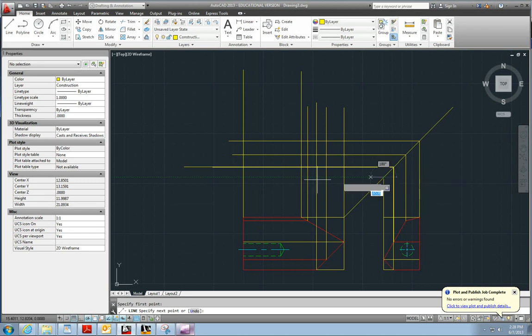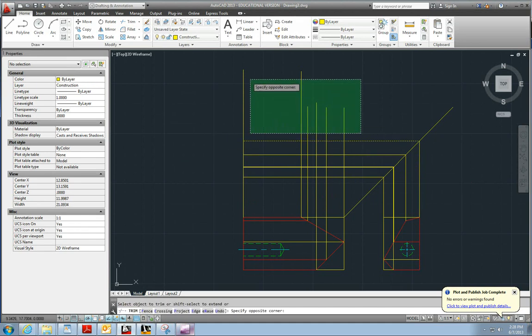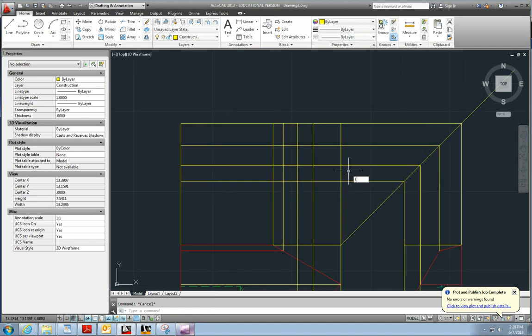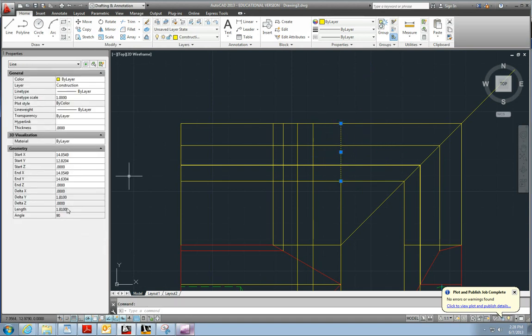So the reason we use a 45-degree miter line, it has to be exactly 45 degrees, but all the measurements, the depth measurements, will transfer from the right side view to the top view, or the top view to the right side view. So that's a good technique, in my opinion, to accurately transfer dimensions. I think I've done this in a previous video, but if I were to draw a line from here to here, the length of that line is 1.81.